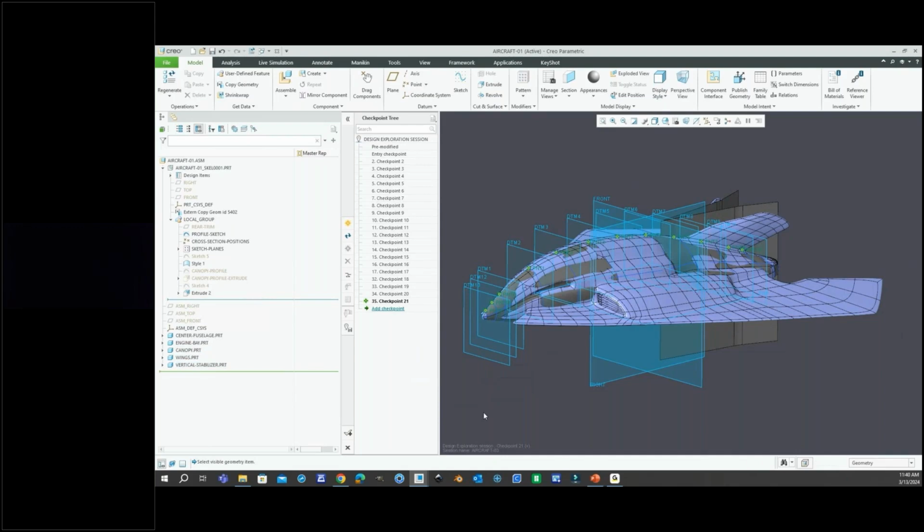Make any adjustments that would need to be made for each component. But the idea is to start off with a skeleton model with the surfaces of every one of these components and then share them here so that people are working in the right space claims, they have the right data, and we're following that top-down design philosophy.